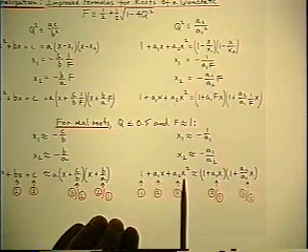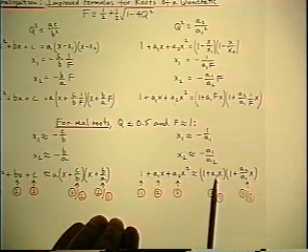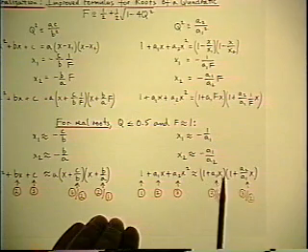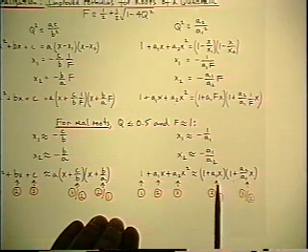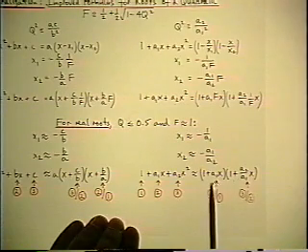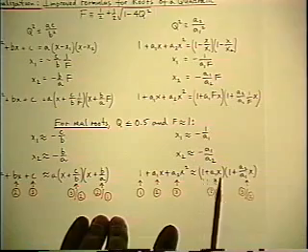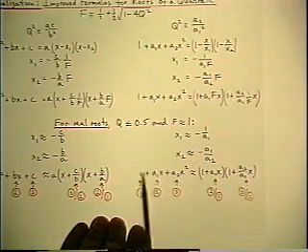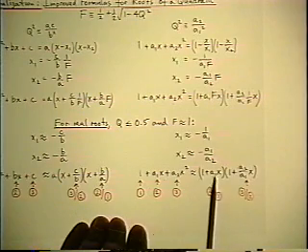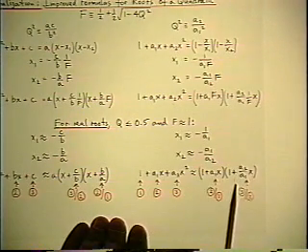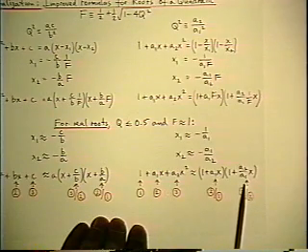Whenever you have a quadratic equation in this format, if the roots are real and well separated, which means the Q is a long way below 0.5, the quadratic approximately factors into these two simple terms. And notice the first factor is identical to the first two terms of the original quadratic. And the second factor is found as the ratio of the third to the second coefficient.